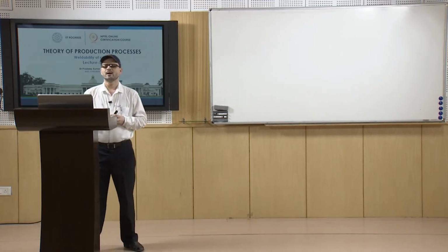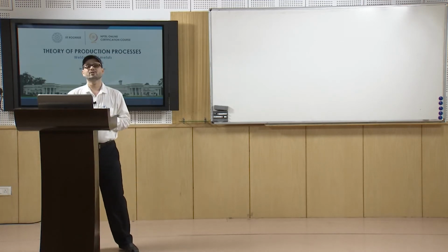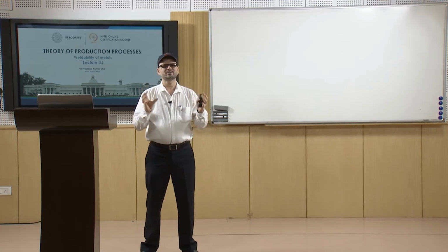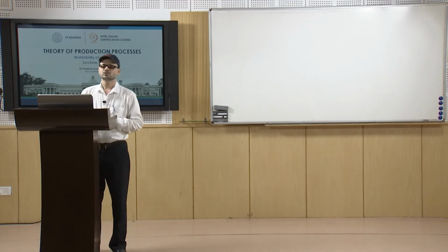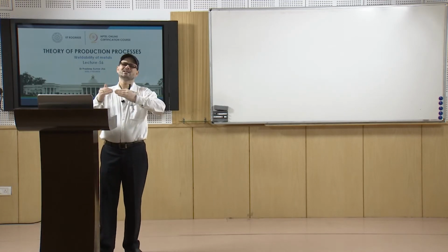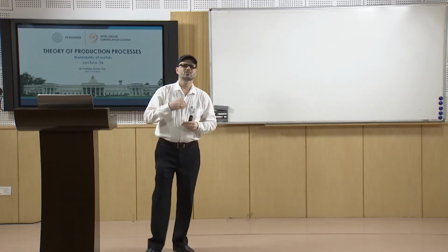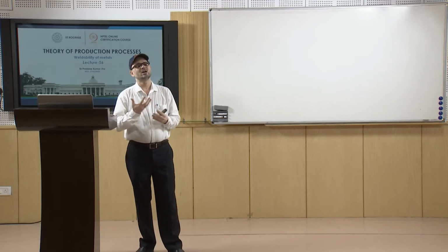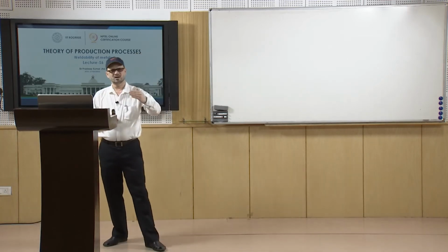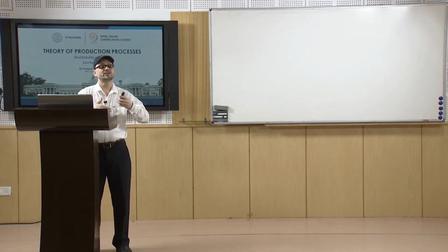So, that is why we talk about metallurgical compatibility, and this is a very important point, because if they are not metallurgically compatible, between the plate material and the material in the weld pool, and they do not have good compatibility, then you may have deposition of carbides along the grain boundaries that may induce brittle behavior of the material, or you may have different undesirable phases which may decrease the ductility or the ductile brittle transition temperature. So, there may be an effect on those points. Metallurgical compatibility is that way very important when we talk about weldability.